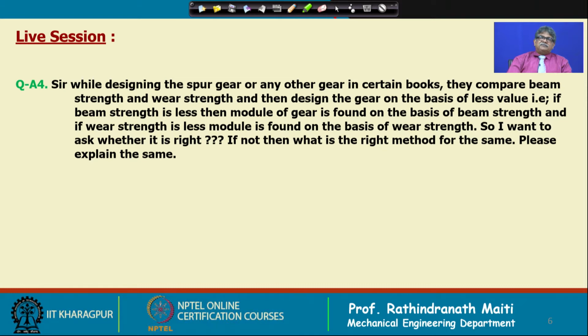The reason is that the design is made in such a way that it is slightly over designed. There is no question of optimization. General purpose industrial gears are designed for infinite life, you can say. So, once they can take the bending load even with the dynamic load, they normally will not fail, unless it reaches the alternating load, that is the fatigue point, and these are not usual.